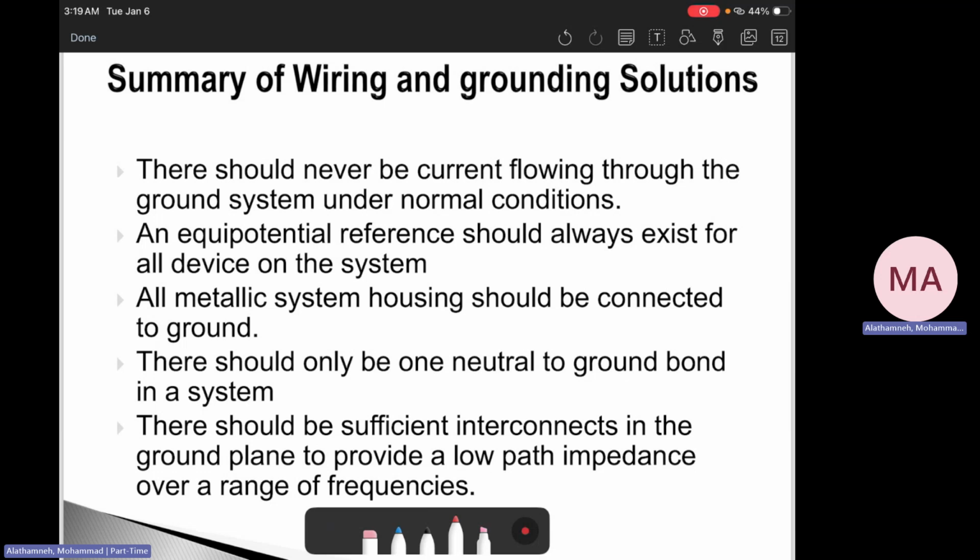Grounding and bonding standards repeatedly emphasize controlling where system grounding is applied. The other thing is enough interconnects. It's not only about the 50 hertz or the DC components, but it's also related to higher frequencies. A good ground system is a low impedance network, not a single wire. It can be a network, or act as a transmission line. So we need to consider tightening and re-terminating neutrals, to improve the power quality. That's one of the things that you need to worry about.